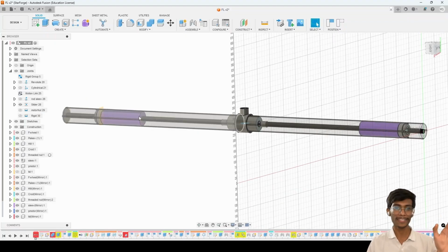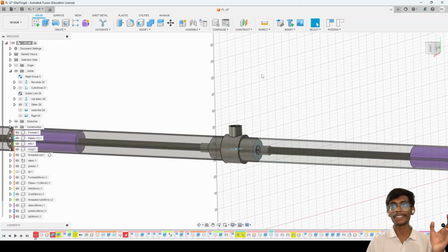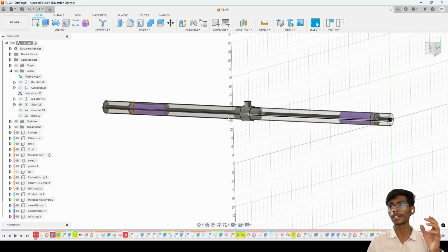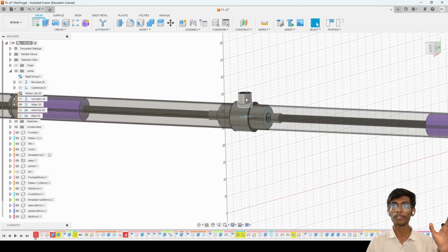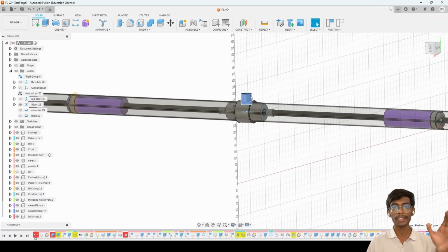So to counteract that, what we are going to do is have two counter rotating flywheels which would cancel each other's torque. And what it is going to do is keep the system stable during the startup. And then we can dynamically adjust the center of mass of the system. And the pivot would lie around here. And having a dynamic center of mass helps us take the system from still to moving.